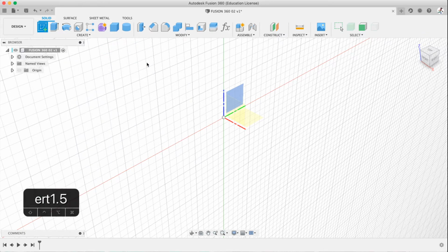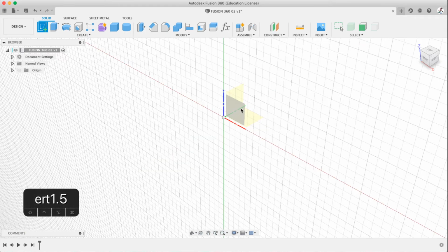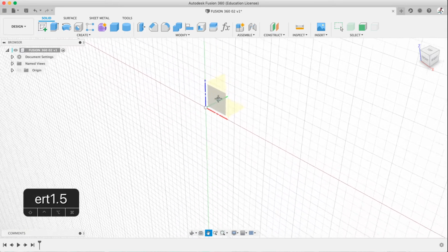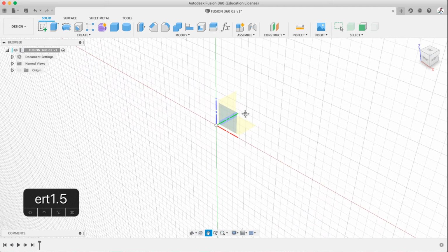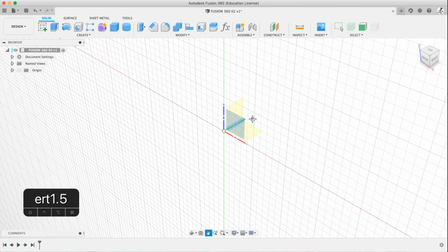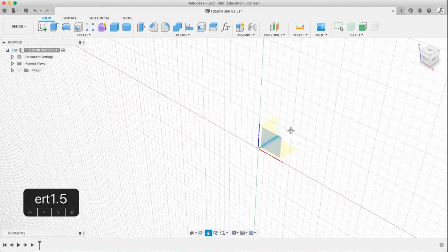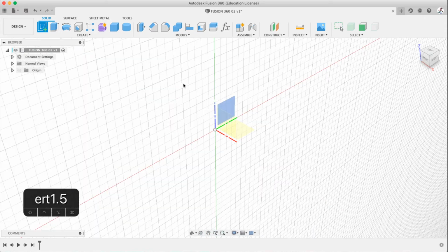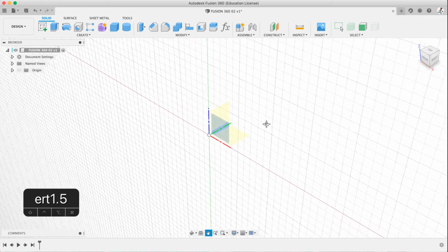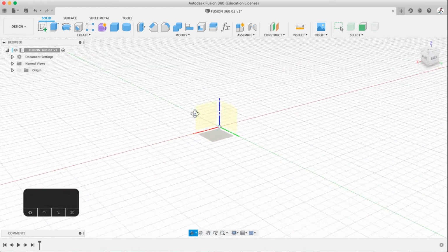I repeat things a lot. In the first video, we saw this, and I'll show you how to navigate around. Just to repeat myself, I have the middle mouse button. So you're going to need a mouse wheel in the middle of the mouse, and just click it down. It should be a button as well. If it's not a button, please get a mouse with a wheel / button. You just push it down and you drag. This is not moving the actual object or the document. You're moving the camera. And then hold shift and click the mouse button and move, and you can rotate around.